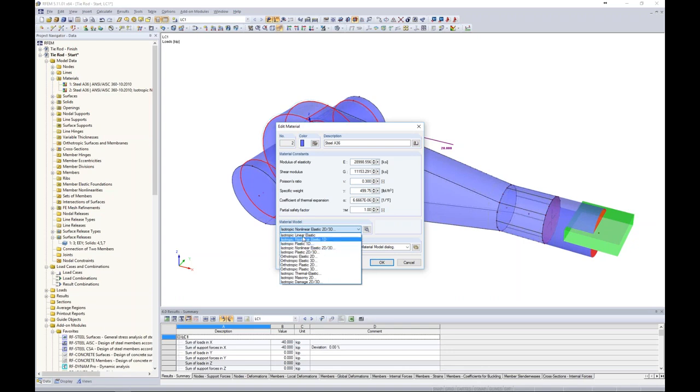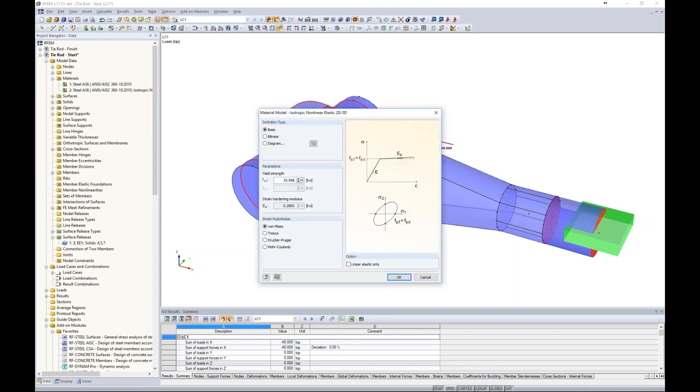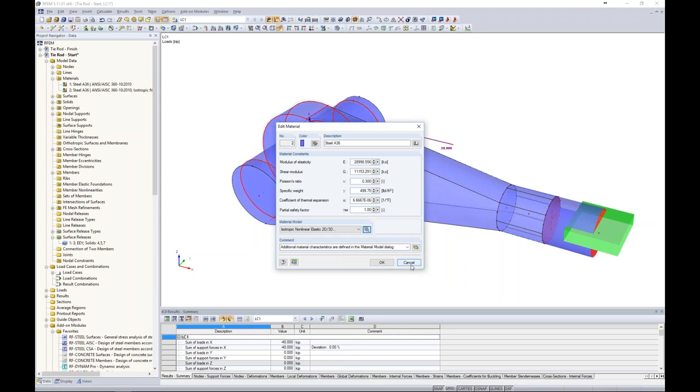So that will release all of these various options to do a nonlinear material analysis. So for example, you can see here in our details, which if this opens up, I don't know why there's a little bit of a lag time. It must be the FE elements, but we can see here the yield strength is set to 36 KSI more or less just from our steel A36 material.